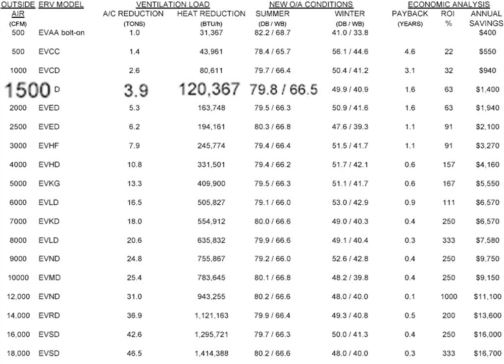I basically neutralized it. On this same example, on a minus 10 degree day, I'm going to be bringing in 50 degrees discharge off the wheel. So in this example, I got a 60 degree rise off of this particular wheel, which is substantial when you think about it. I'm getting 60 degrees of free heat. Now, in some cases, 50-degree discharge may be enough to avoid my unit from even kicking heat on. In other cases, I'm going to have to put the heat on, but in much smaller cycles.